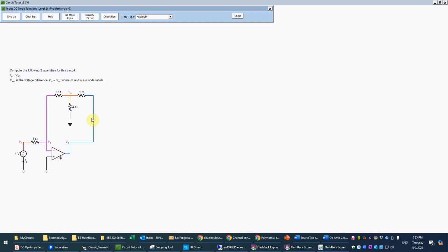However, things are a little bit different because we don't have a simple feedback resistor. Instead, we have this sort of T network where one branch goes to ground, which is interesting. And remember that all these different ground symbols, like here and here and here, as well as the ones on the power supplies, the positive and negative power supplies for the op-amp, which are not shown explicitly here but represented indirectly by this little ground symbol, all those grounds are connected together by invisible wires. So this is actually a more complicated circuit than it looks.